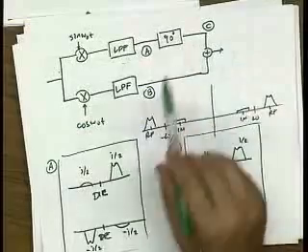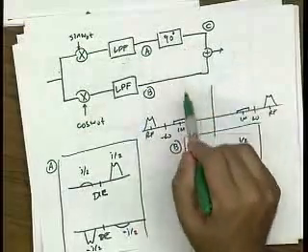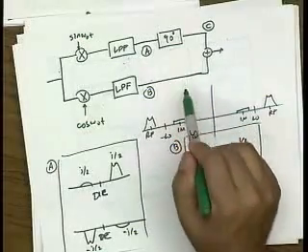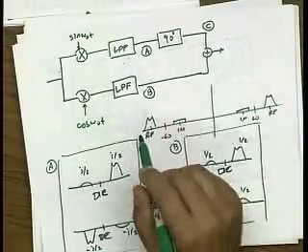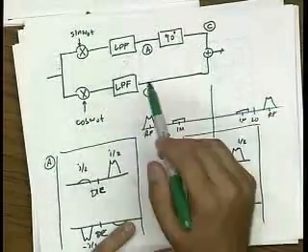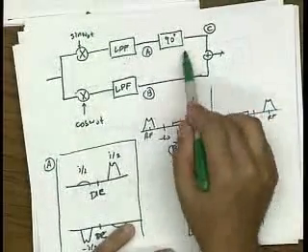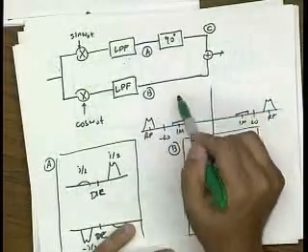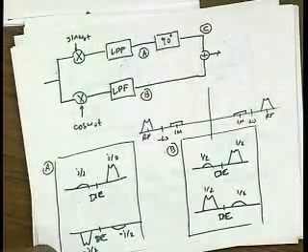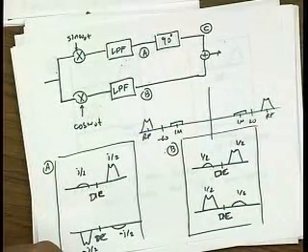But in reality, of course, if we build these with circuits, there's going to be an issue with matching the phase and magnitude in these two paths. So right away, you can see that this implementation here is already asymmetric because one path has a 90 degree shift in it and the other one doesn't. Anyone think of a simple way of solving that problem?